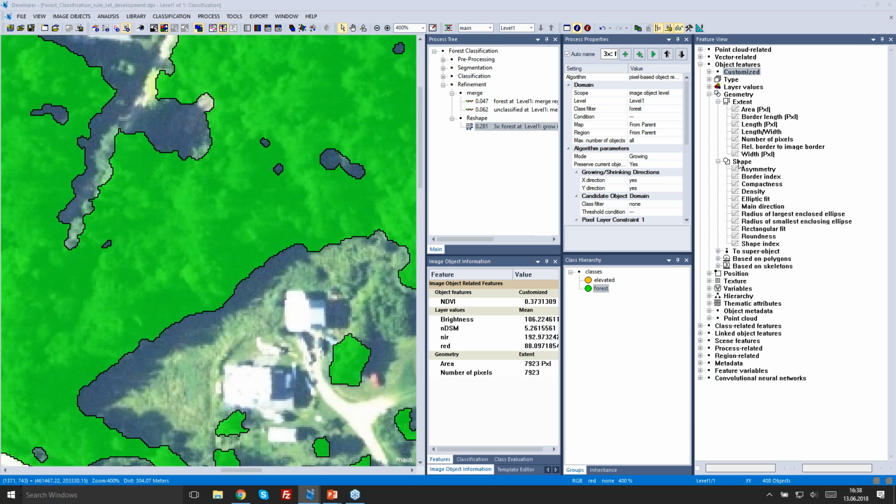The crowd seems to be warming up. One question that we have here is regarding the rasterized point cloud algorithm. Here we use that rasterized point cloud algorithm to create our NDSM layer because this point cloud was a normalized point cloud to begin with. The question is, when we rasterize the point cloud, what is then the resolution? What is that raster cell size within the raster file that we create within eCognition?